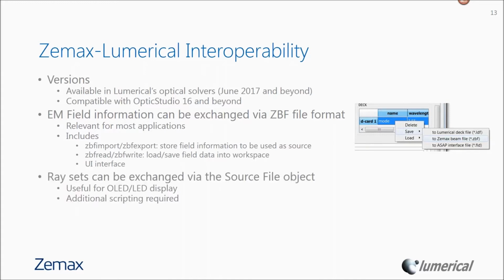For some applications, the direct exchange of EM field information doesn't make a lot of sense. For example, for the OLED and LED display applications that we went over before, you would actually need to convert the field information into a ray set first before importing it into OpticStudio using a source file object. And for now, this does require some additional scripting.